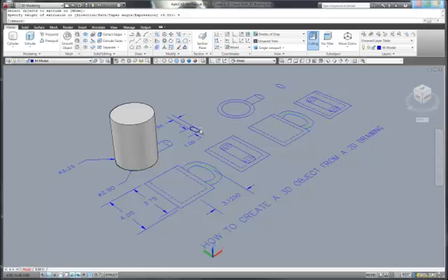Now what I want to do is create the handle. I have this shape here that I've drawn, which is a simple ellipse that's 1 inch by a half inch, and I have created this shape that I wanted and defined a center line in it. So I'm going to use that center line, and now I'm going to move it into this plane. I need to move it from this plane here to this third dimension, to this Z plane.